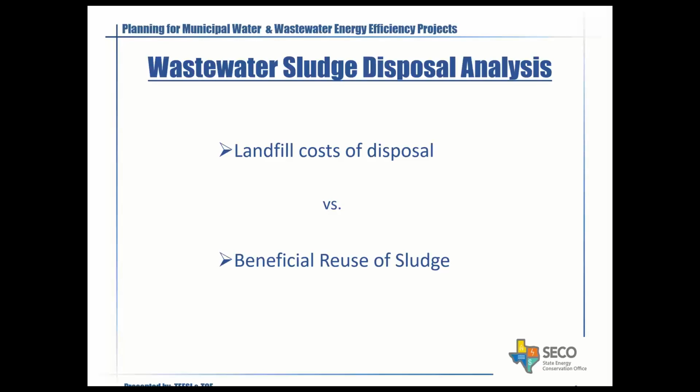So it's a lot of work to reuse sludge, but it does pay for itself over the years. So keep in mind when you're looking at landfill costs, you can do some agriculture and have beneficial reuse that will pay back relatively quickly.